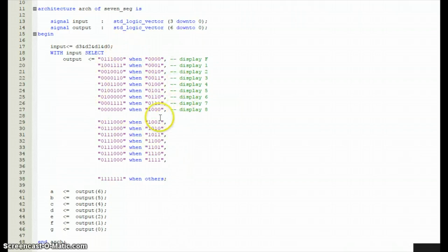There are a total of 16 combinations as we have 4 inputs. 4 inputs is equivalent to 2 power of 4, which is 16-bit output. However, we only use 9-bit outputs. The 9-bit output is derived from the truth table. The remaining 7-bit output, we put it as F. At the bottom section is our output vector. It has to be separated to make individual pin output.